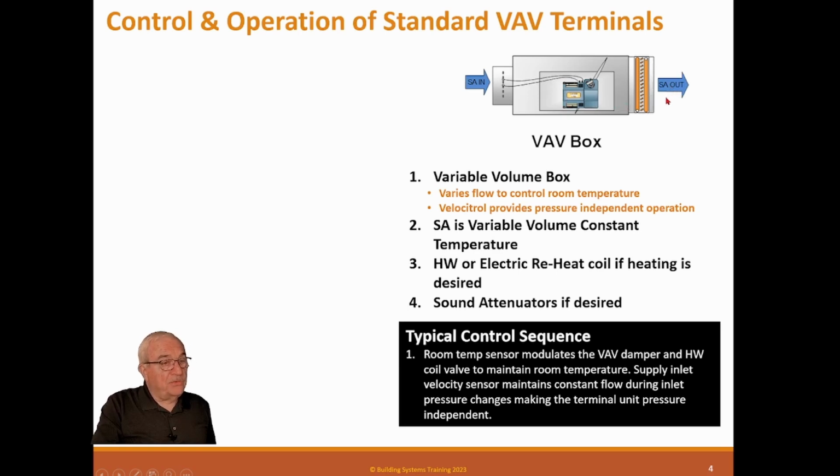To be quite truthful, the minimum set point is more important than the maximum set point. The reason is most boxes hang out around the 60 to 75% place and eventually down around minimum if it's a 30% box, more than it will at 100%. So that's one of the misnomers about sizing boxes. A lot of engineers believe bigger is better, and with sizing boxes, it is not. They need to be sized correctly.